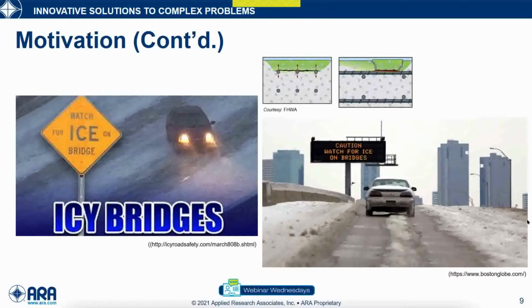We can also eliminate corrosion, because typically we apply de-icing chemical agents on bridges, and the chemicals penetrate through shrinkage cracks, and when they touch the steel, corrosion starts, which causes delamination and significantly reduces the life of the bridges. So we're trying to eliminate all of these accidents, and also extend the surface life of bridges by implementing this technology.